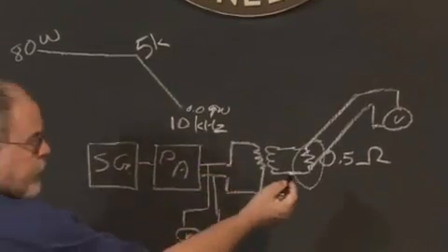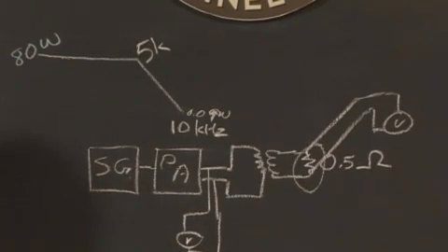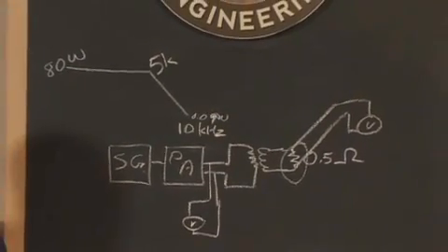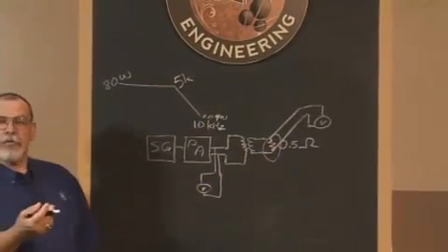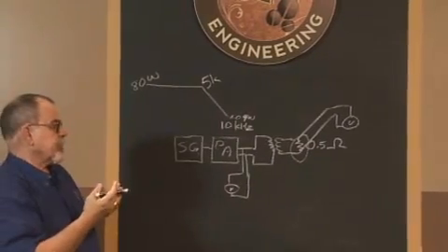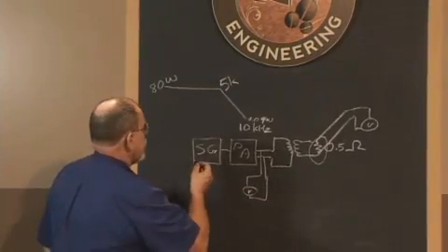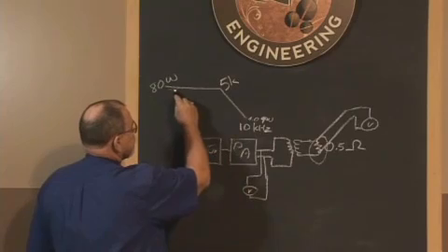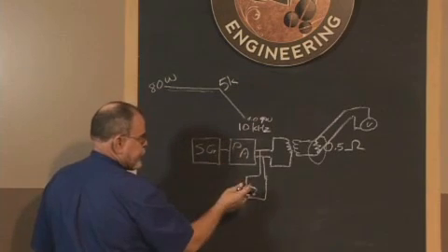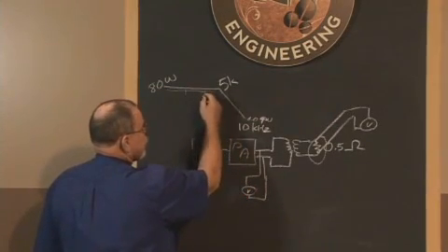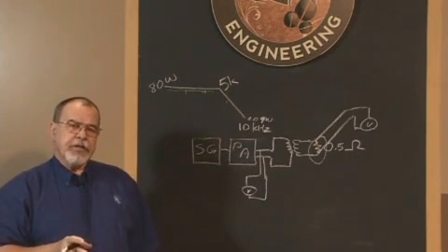Now, our point is to generate this power here. We're trying to measure with a voltmeter, so prior to test, we will calculate those levels that we need to do. For 80 watts and half ohm, we need to have 6.32 volts RMS. Now that will be providing the 80 watt dissipation in the resistor. So let us consider doing that. And we tune through the frequency range and the calibration, verifying the voltmeter settings. When we have to change the levels, we need to take another measurement point so we can record where we are. We're doing a susceptibility test.